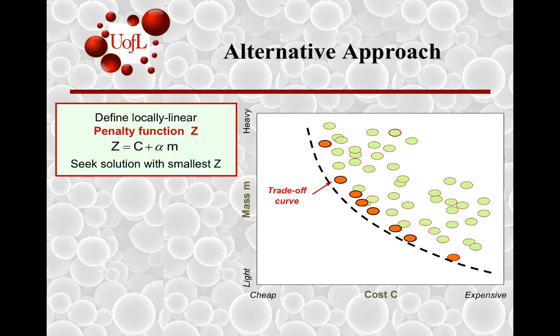So that was a case where we plotted 2 property indices on a log-log scale and used a coupling line to take into account different designs based on variations in load, variations in dimension, and variations in material attributes.